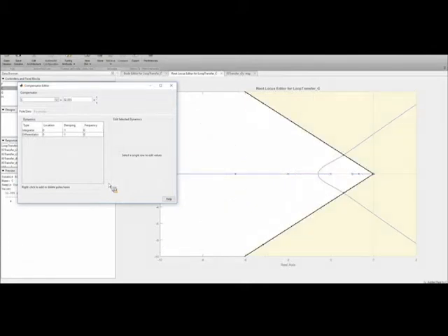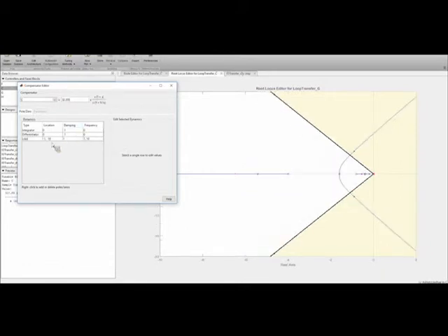All right. And all these other things. What we're going to mostly be talking about is what are called lead lag controllers. We'll get to that in the next lecture. But a lead lag controller has both a zero and a pole associated with it. And we'll talk about that a lot in the next lecture. But these are dynamics we can add to our controller. And then the proportionality between all of them would be this gain out front.